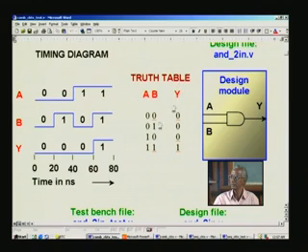This truth table for the AND gate is given here for various combinations of AB, and you can also depict the same thing in terms of a timing diagram, which is shown on the left. A, B and Y are exactly the same sequence, except you need to read it vertically instead of horizontally. You see these 3 entries 000 here, and that is precisely appearing here, and the next entry 010 is here, and 100 followed by 111 here, exactly the same thing.